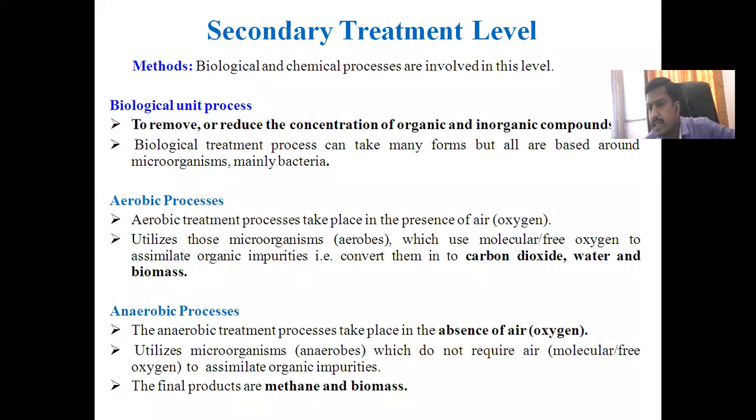So please remember this process once again. In the aerobic process, this process happens in the presence of air. How does it work? The microorganisms present in that wastewater will use the free oxygen to assimilate the organic impurities.